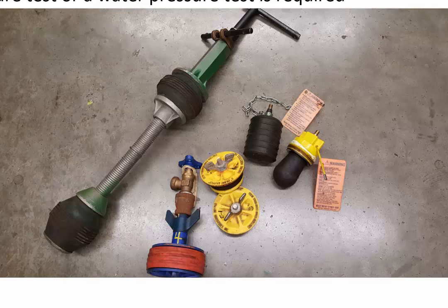So in this illustration, we can see some of the different test balls and test adapters that can be used to plug the lower end of a drainage system. This larger one is for a Y fitting. Some of these are for test tees and different fittings, or different assemblies that can be used for the test. So these would go at the lower part of the system, and then the system would be filled with water to the upper portions of the venting system, or for sections of a system as required by subsection 236.